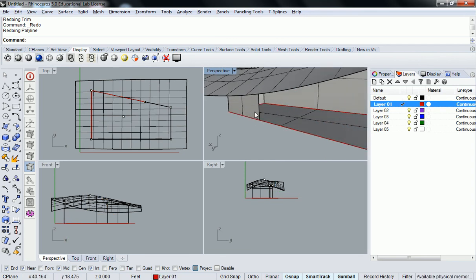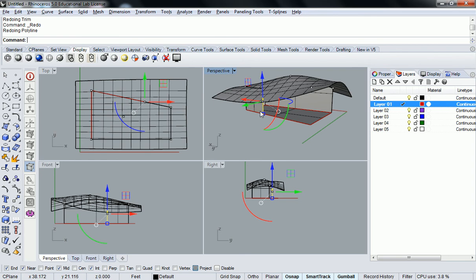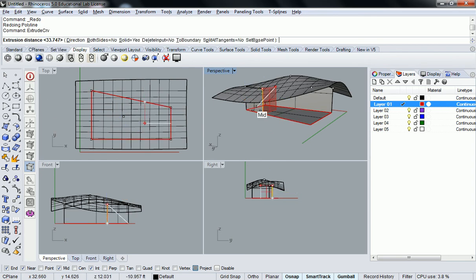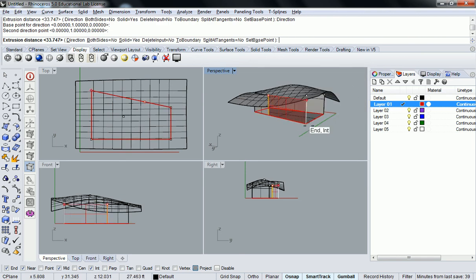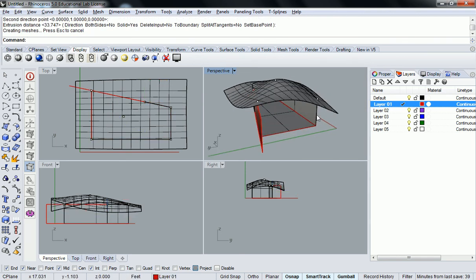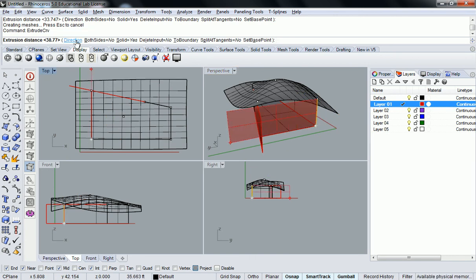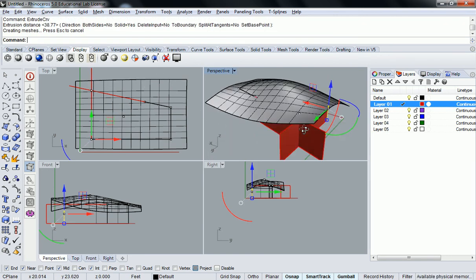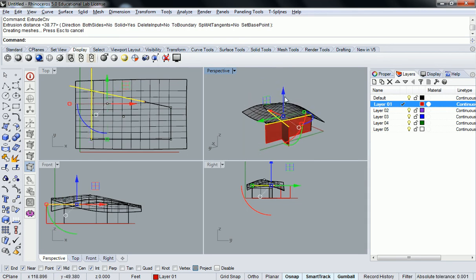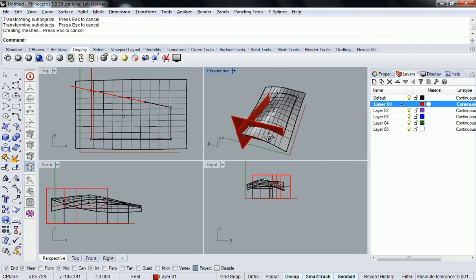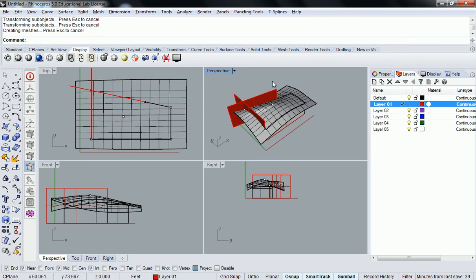Yeah. So creating new walls essentially would just mean that you have to extrude curve, set the direction, yank it off, do the same thing over here. Oh, look at that. It's already on the edge. Then you just do the same thing as the rest of your walls, where you grab those edges and pull it up. And then you have a full profile.